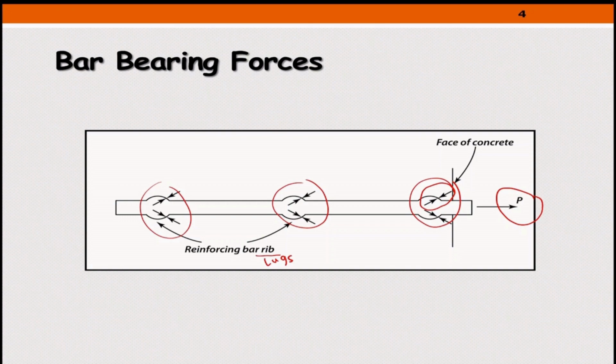This is one measure we take, and it's now implemented in the codes of practice, that smooth bars without deformation or ribs aren't allowed. But there are other factors that we also need to take into consideration, like development length.